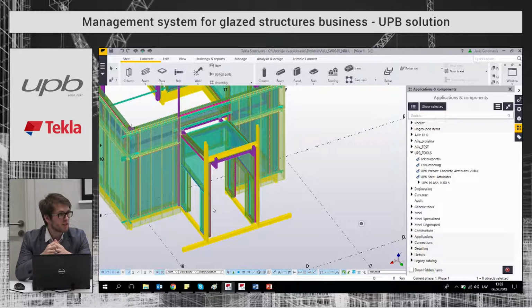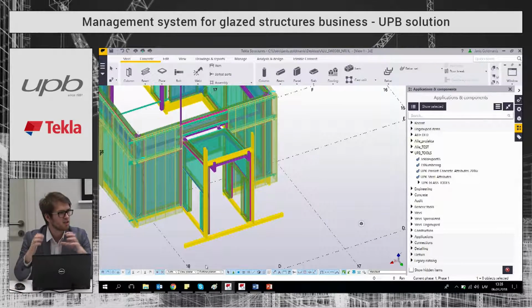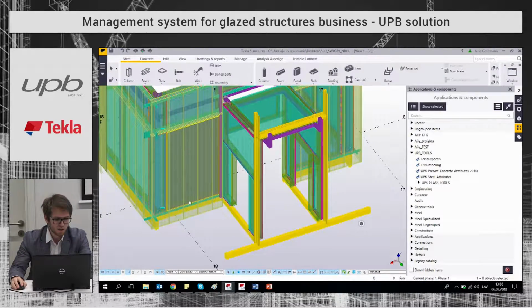The first tool that we required was because Tekla comes only with heavy profiles, like IPE and HEA beams and columns, and it doesn't have those thousands of aluminium profiles. So we have developed a tool that converts any DXF profile, any shape, to a table profile automatically. The next step was that we wanted to quickly create a frame, and we have developed a tool.